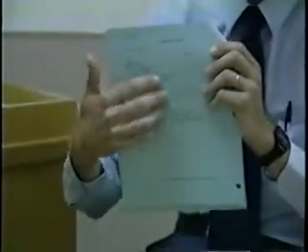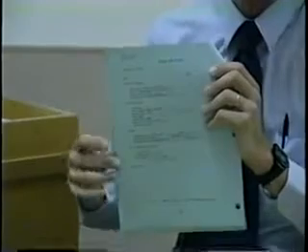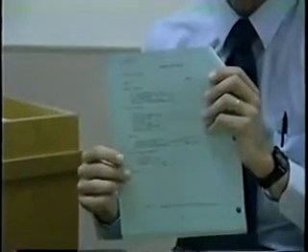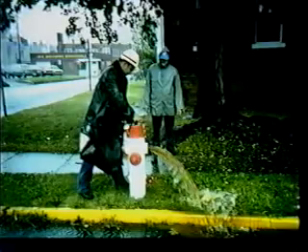It's published in Corps of Engineer Technical Letter 1110-2-297, and it has blanks for the kinds of information you need to be sure you collect while you're out in the field. Such things as the residual pressures with no hydrants flowing, one hydrant flowing, the kind of information that you need to run a good test. Okay, now let's run some tests.